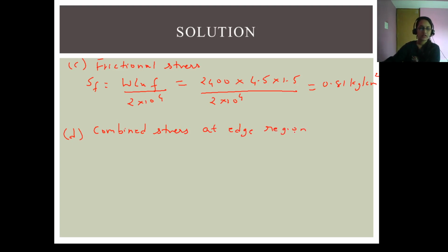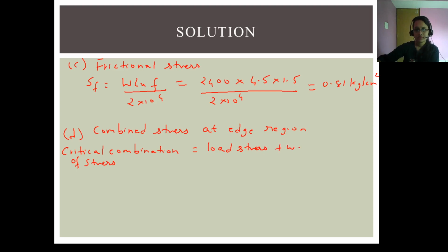Critical combination of the stress during the summer midday equals load stress plus warping stress minus the frictional stress.